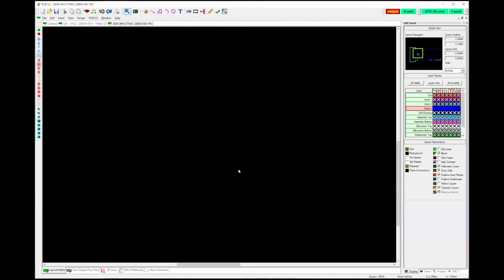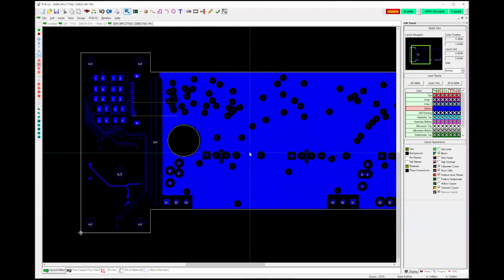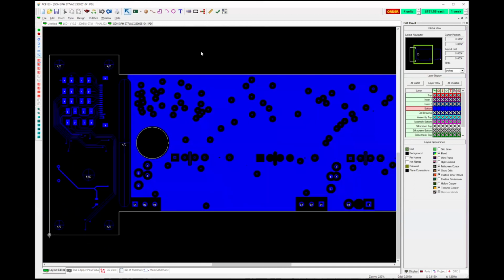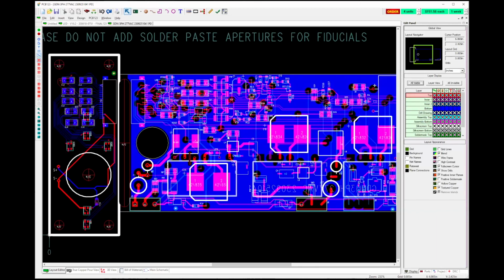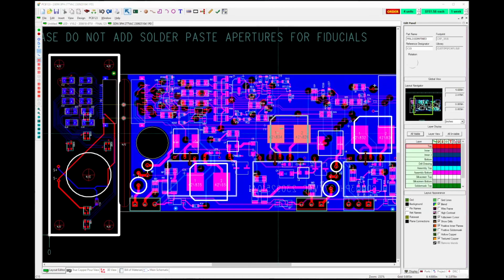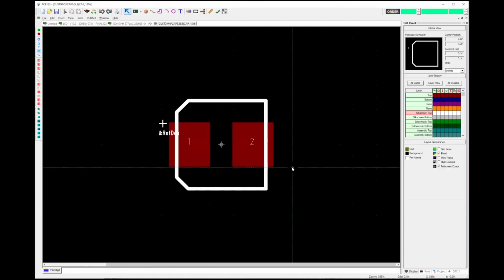What I can do is go in and, if nobody minds, show you how to make a footprint. It's really pretty simple. I always start with a part that's already there. Let's say I want a surface mount electrolytic capacitor. I've got one here, so I know that shape is kind of what I want, but I want it to be smaller and have smaller pads. So I'll say edit footprint. That's this selection right there. It'll pop up another window altogether.